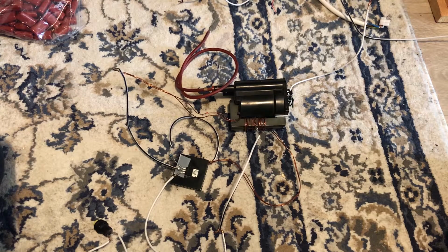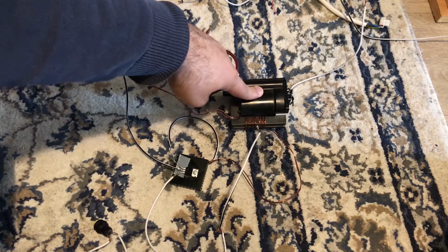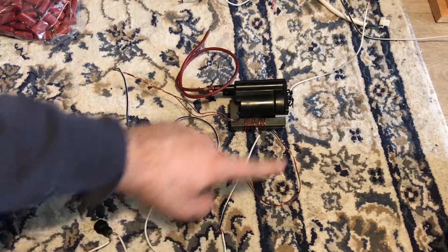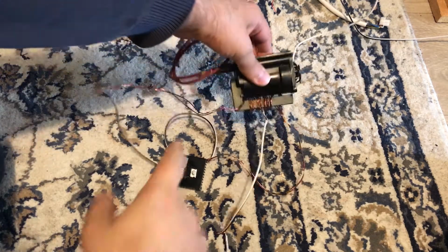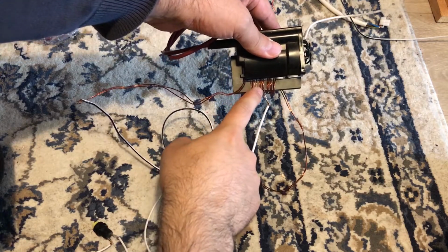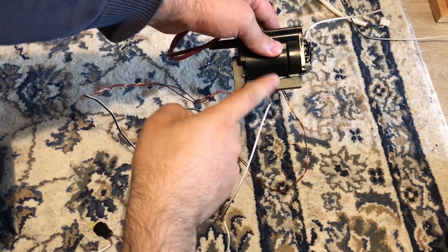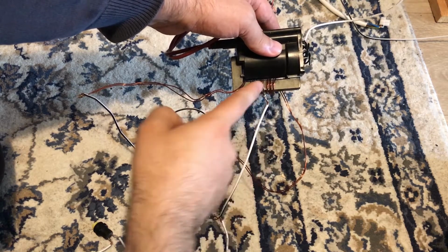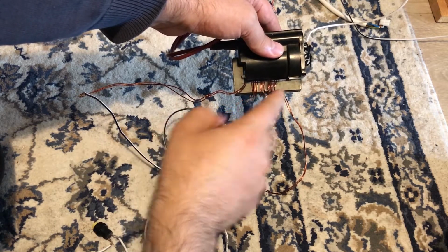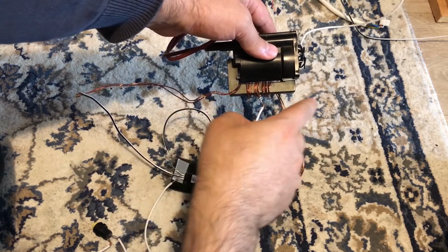For the power supply, I decided to build this very simple high voltage power supply. It's a weak power supply, but at the beginning for us it is a good choice. This is a flyback transformer. We have a simple oscillator circuit here. This primary side has a main winding which has 4 turns and then a feedback winding which has 3 turns. So the winding will wrap up to here, and then you take this point and continue another 3 turns.